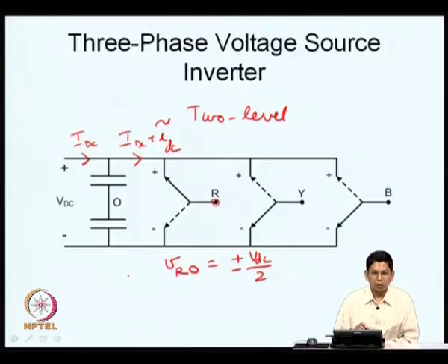So, what we are going to see is that the ripple is flowing through the capacitance. Now, the power flow is in which direction? It is from the DC side to the AC side, that is what it means. And here again you would see the power factor on the load side. If you look at the fundamental voltage and the fundamental current, they will be close to one another, their phase will be close to 0 or within 90 degrees plus or minus, and therefore the power is flowing in one direction, from DC to AC.